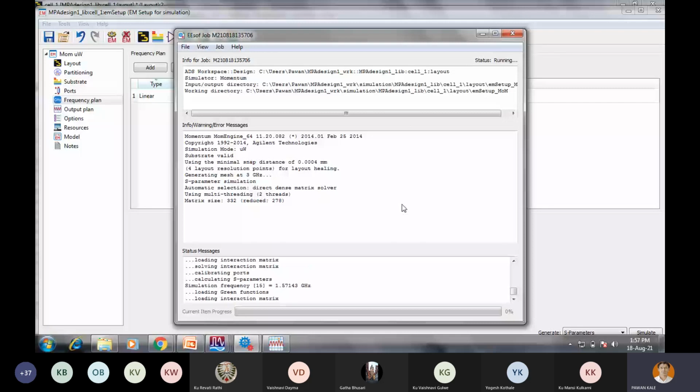You know for what purpose 2.4 gigahertz frequency is useful? I think mostly we are using Wi-Fi, Bluetooth applications like. So Wi-Fi, Bluetooth, all these are actually the kind of applications which are working over 2.4 gigahertz frequency. What does it mean? The antenna that we have designed, it can be useful for which application? Wi-Fi application. Is that okay? So it is useful for Wi-Fi, but it must be resonating at 2.4 gigahertz frequency. Let's see whether it is resonating at 2.4 or not.